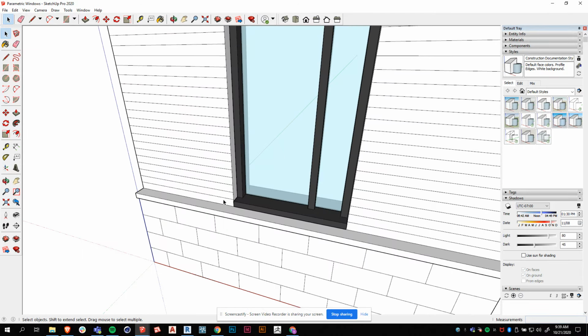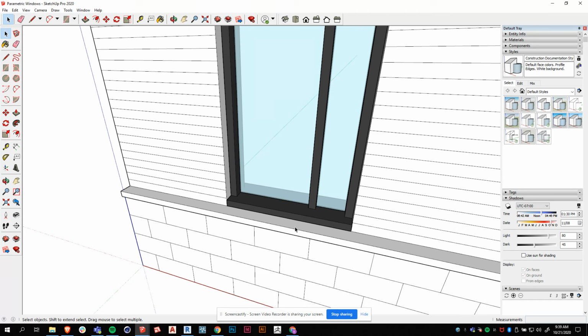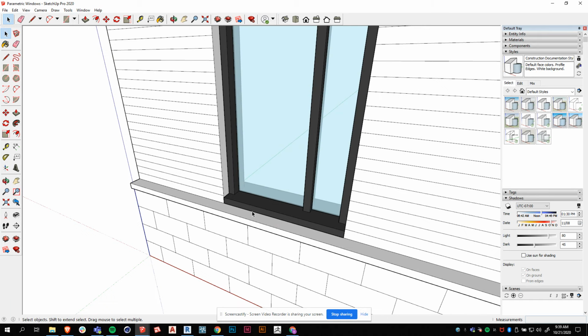And then I want to do another reference plane that is flush with this plane to define the height. Okay, so I could make a shape on the sill reference plane, extrude it up, or I can make a shape on the left reference plane and extrude it to the right. I think for this one, I'm going to do the left side and extrude it to the right. Okay. And as I work through this, you'll sort of see how this is done.